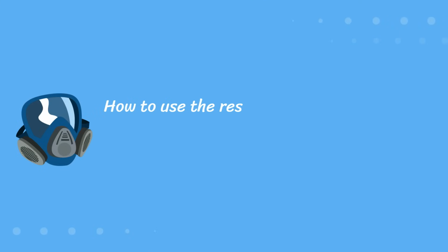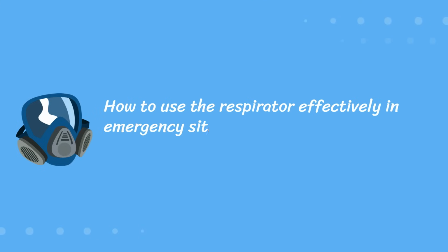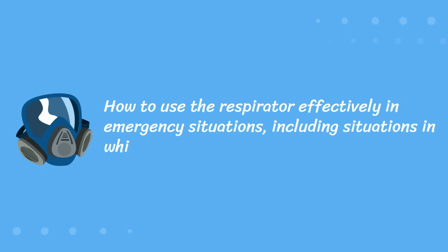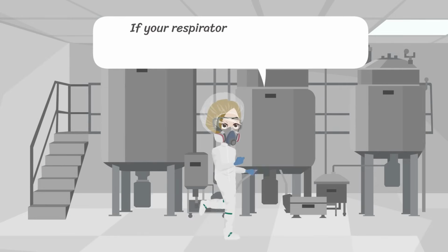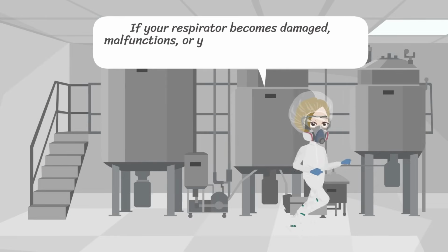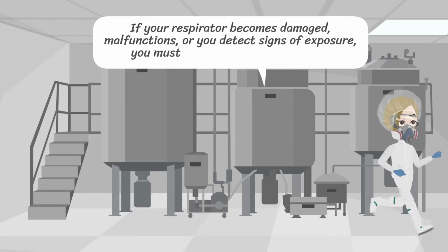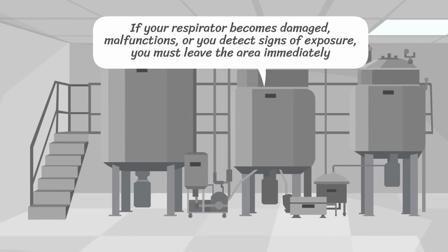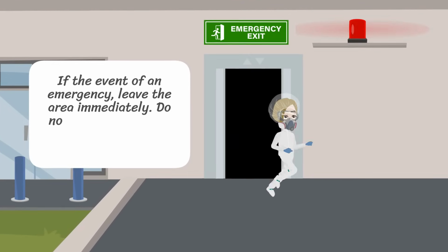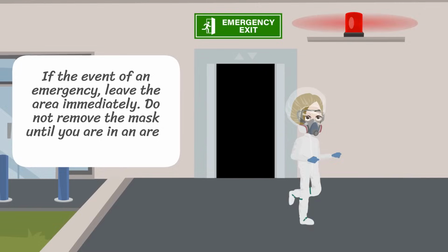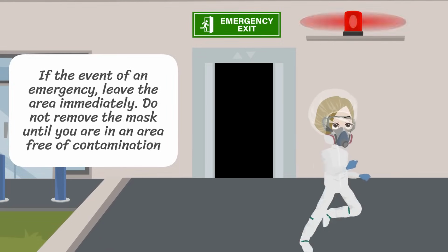How to use the respirator effectively in emergency situations, including situations in which the respirator malfunctions. If your respirator becomes damaged, malfunctions, or you detect signs of exposure, you must leave the area immediately. In the event of an emergency, leave the area immediately. Do not remove the mask until you are in an area free of contamination.